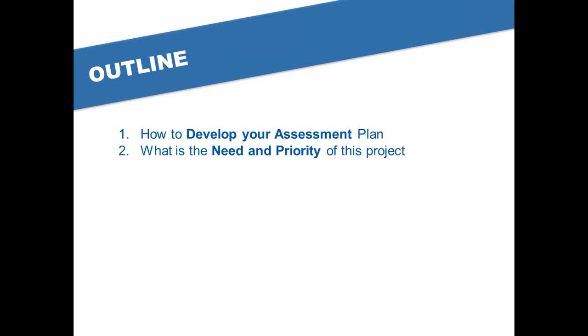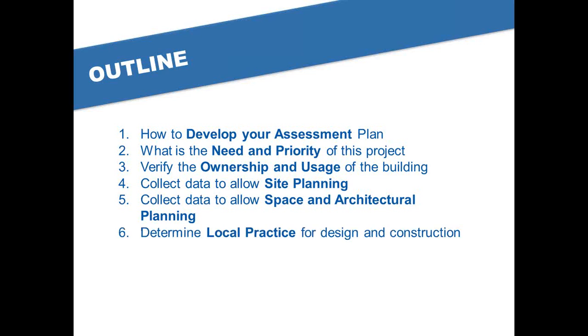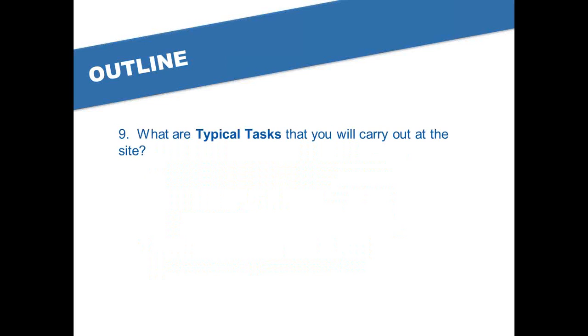And then after that, the specific things that you're going to need to find out during your assessment: what is the need and priority of the project, verifying the ownership and usage of the building, collecting data to allow site planning, and then starting to get into some of the stuff for the building itself, space and architectural planning, learn about local practice, determine what your governing design criteria would be, and how to assess material properties that will be used in your implementation.